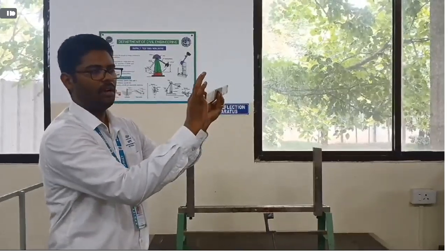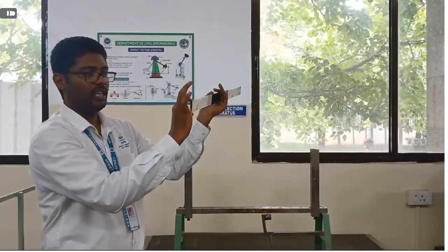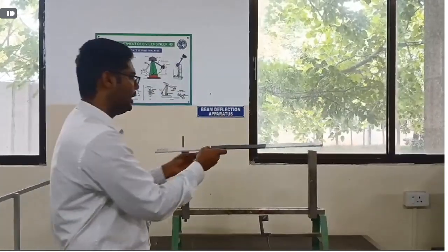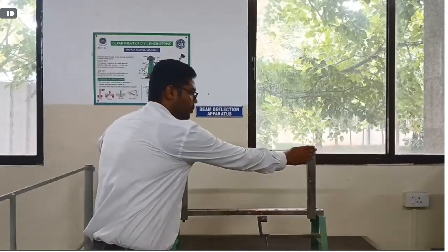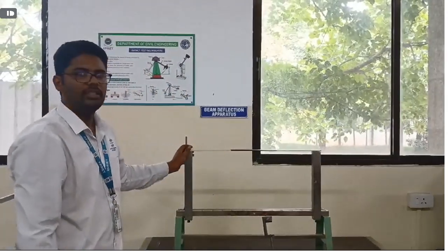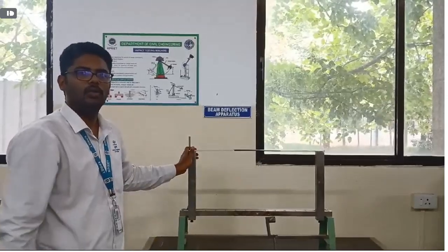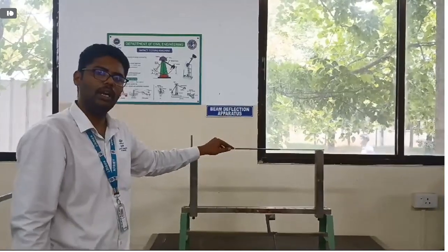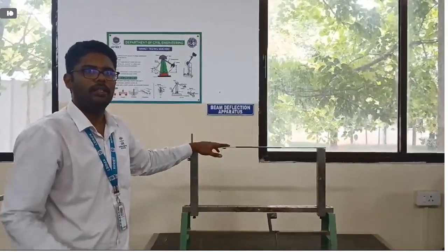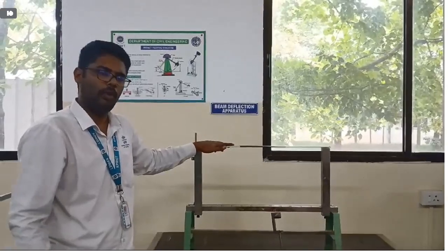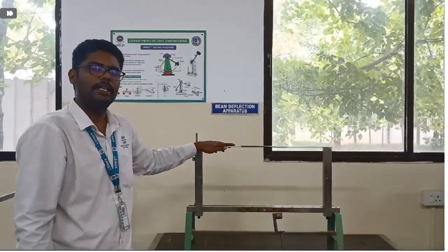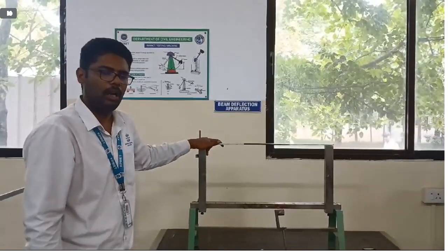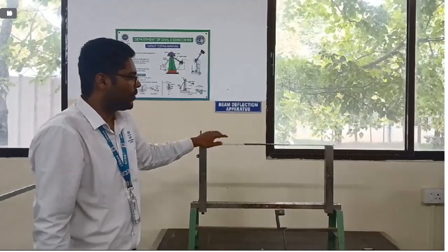In conclusion, understanding the moment of inertia is essential for designing and analyzing structures. For rectangular sections, the height has a significant impact, as it is raised to the third power in the formula. This emphasizes the importance of choosing appropriate dimensions for structural efficiency. The higher the moment of inertia, the greater the resistance of the beam to bending. For example, a tall and narrow rectangular section will have a much higher moment of inertia compared to a short and wide section, assuming the same cross-sectional area.